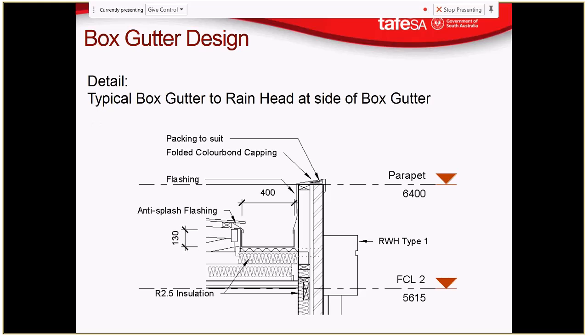So we just have a little flashing up here to help stop any splashing that happens. It's all guided back into there. And also our box gutter can get higher and higher as it goes upstream, and that flashing can accommodate that as well.